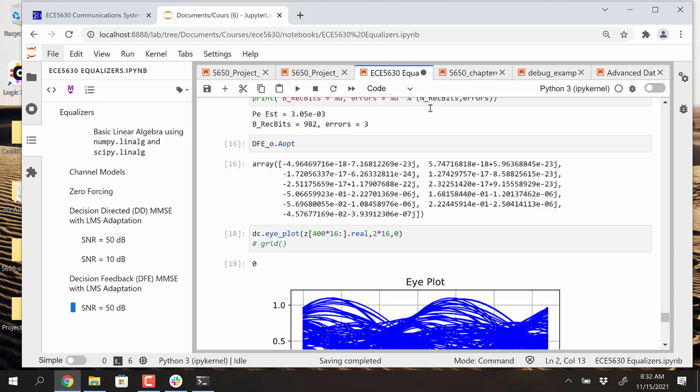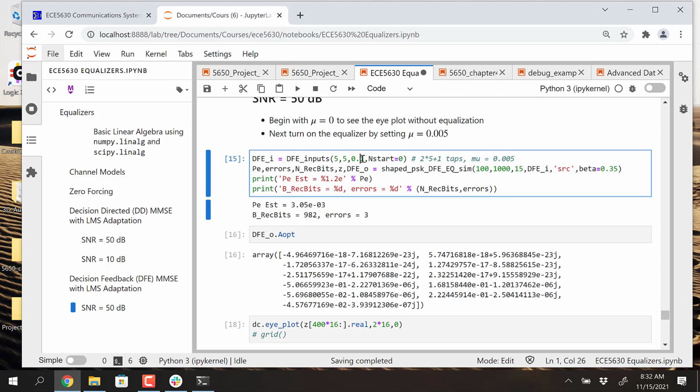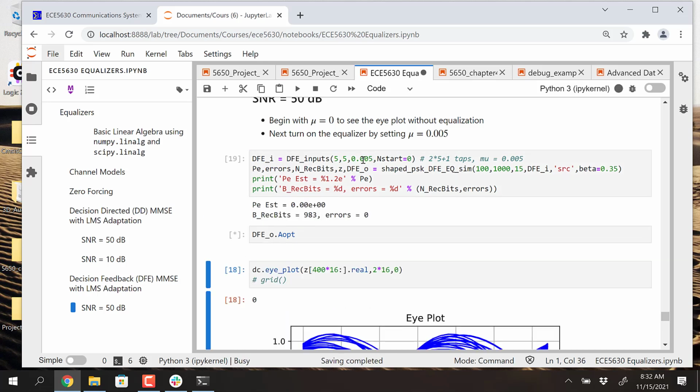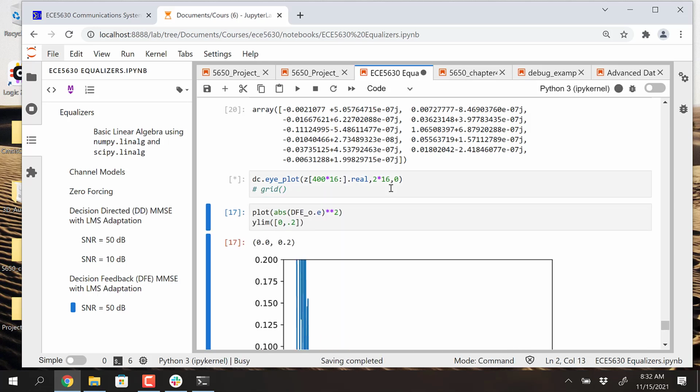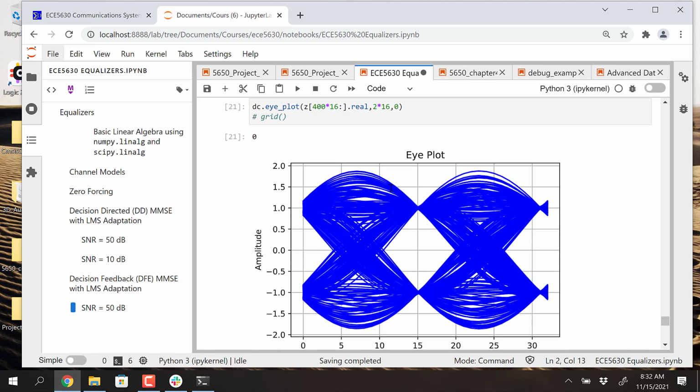But that doesn't look right for the eye pattern plot. So let's take this back down again. I think it may have gone off the track somehow or another. That's pretty much open. So I don't know really what's going on there, why I didn't see that in the error curve. It's finding another minimum, and it's not the correct minimum. But remember, decision feedback is a nonlinear equalizer. So I'm not as familiar with working with DFE and its nonlinear behavior. But that's better than it was working with my bogus results in there.